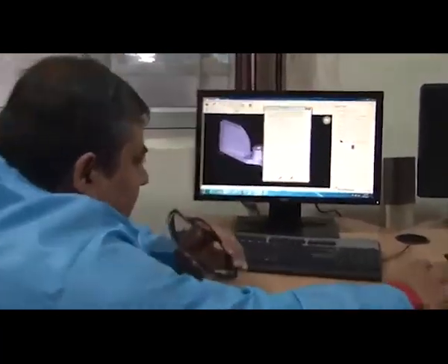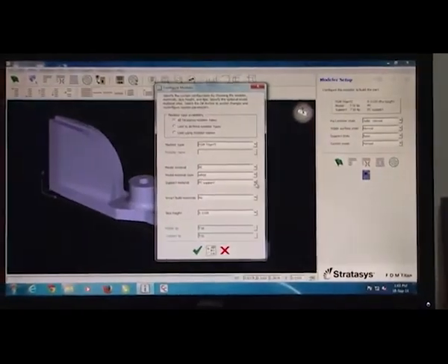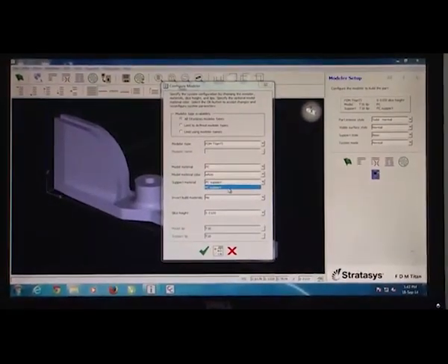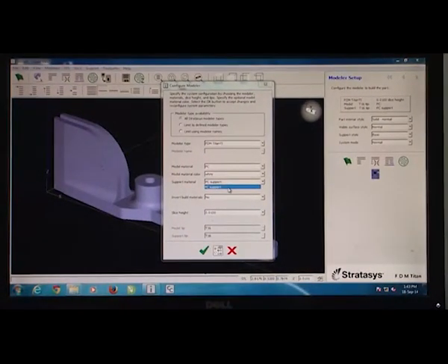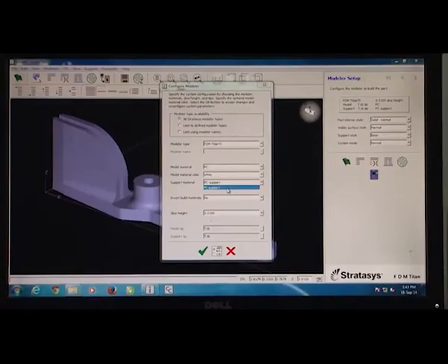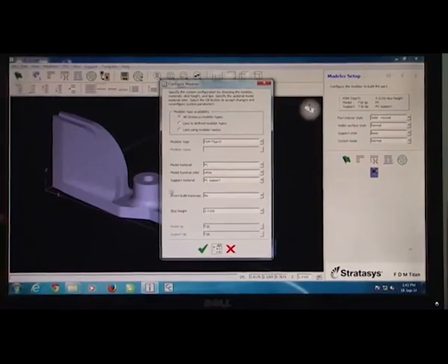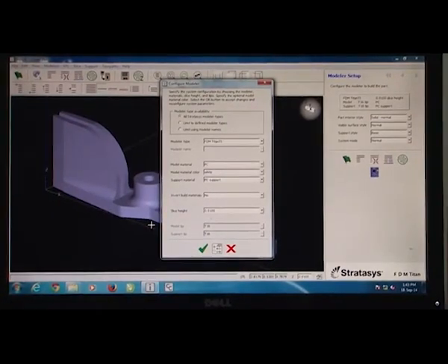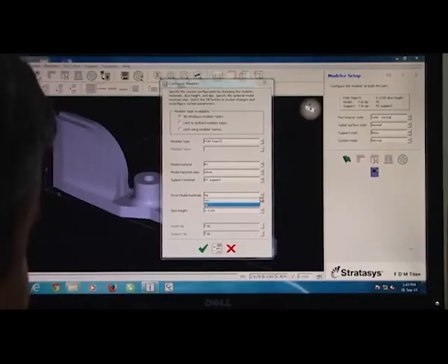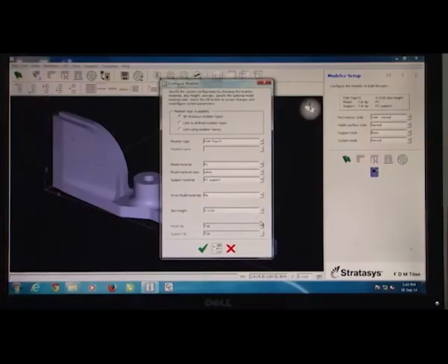So here in this particular case you can see the support material being defined on the polycarbonate. So the option that is being set up in the software is that if there is a PC part, typically the support will also be of the PC, okay. So the PC support is defined here, although you can change it probably by going into the setup of the software, but at this time we want the material to be the same, so we are selecting PC support. Then if you want to really invert any build materials, the answer, yeah, we don't want to do the invert build material option.